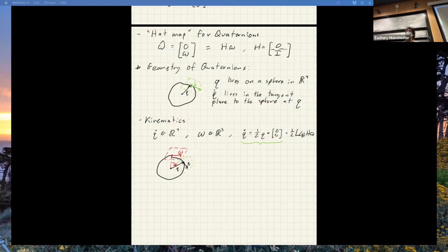The way to think about this is when we have a gyro, that's this omega. The gyro is bolted to your body frame, so you're always measuring it in the body frame. And this Q is rotating you from body to inertial, somewhere else, not at that identity element. So if your body frame is instantaneously lined up with your inertial frame, then your Q in this kinematics is the identity, and Q dot basically is that omega. Does that make sense? Okay, so that's a bunch of weirdo geometry. I don't know if that's insightful or helps at all, but that's kind of what's going on.